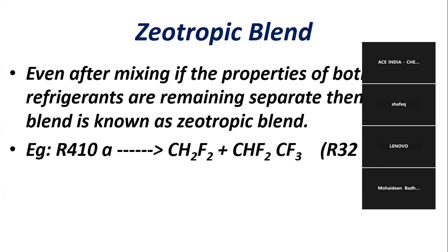That means for small scale applications. Nowadays, compressor manufacturers have started to implement R410A based compressors for residential applications, that means high wall AC and similar units. Okay, so this is the idea of R410A. Then the one problem with R410A is, if you have a high ambient, that means the atmospheric temperature is too high, then you can't prefer R410A with an air cooled method. Due to the high ambient, you can't use an air cooled condenser to cool down the R410A. Instead, you definitely need to provide a water cooled condenser. Okay, clear? So this is the concept of R410A.